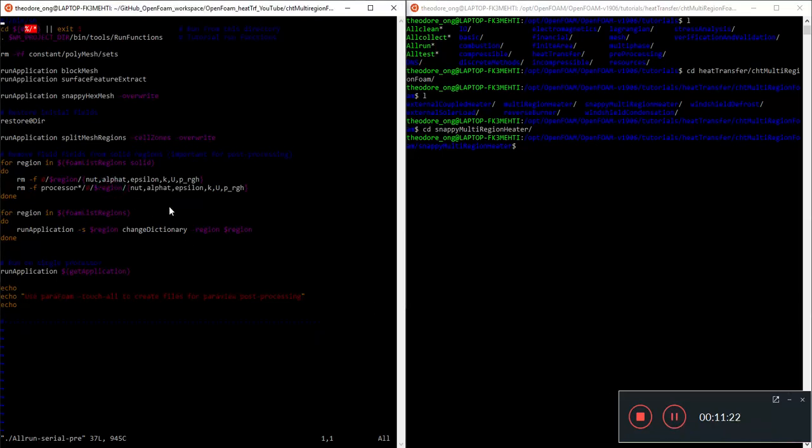And next we want to, of course, change this sh to bash. It should be in insert mode. Write this to OpenFOAM, write this to Ubuntu. Why do I want to do this? Remember, a few videos ago we found that all these brackets won't work in Ubuntu Windows Subsystem for Linux if this thing isn't written properly as hashtag exclamation mark bin bash. So that's the first thing we want to do.